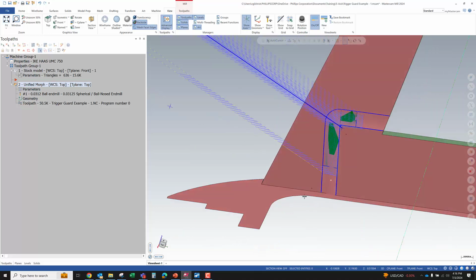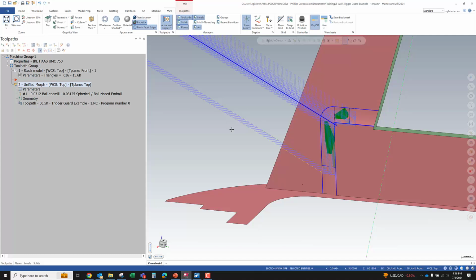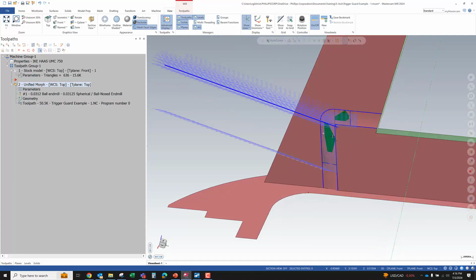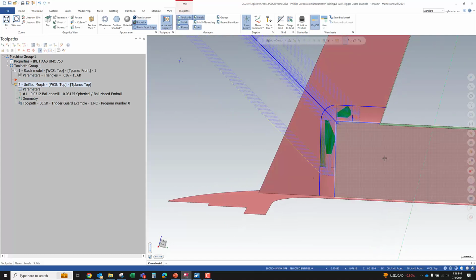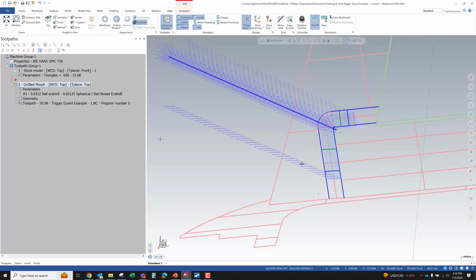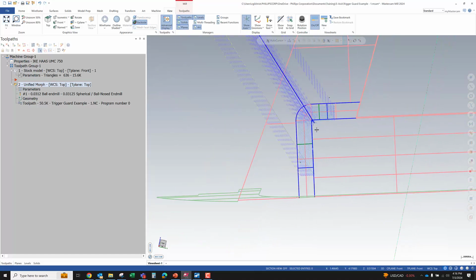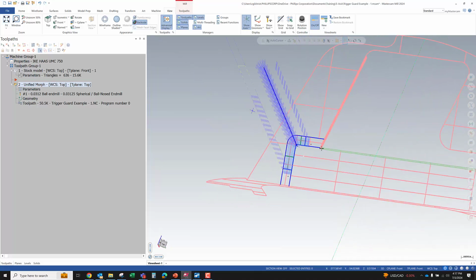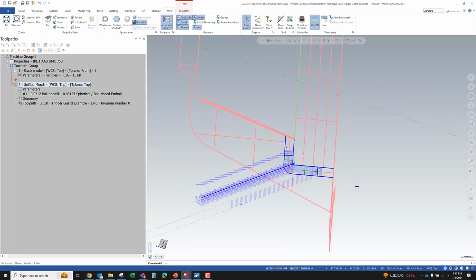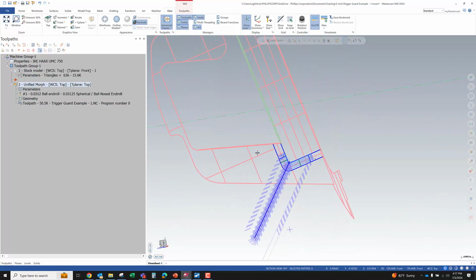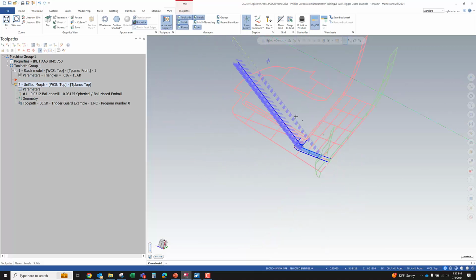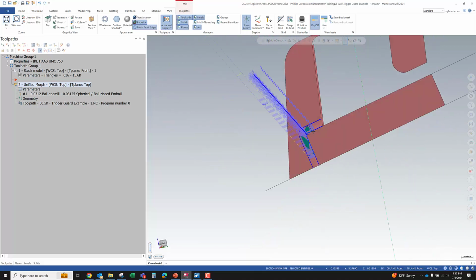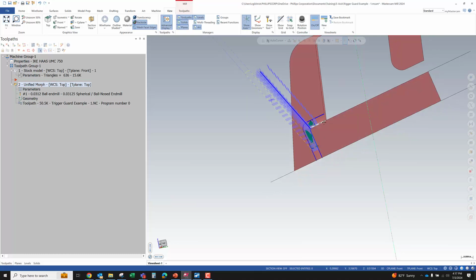So like I said, if you were running this and this has got a little overhang, so maybe when you run your wheel cutter, there's like this triangular chunk of material left over. So in a case like that, if we unshade this, you can see, there's the chain. Yeah, we may have to define it a little differently, but we could easily just chop up one of these surfaces to fit where that piece of stock was that we saw, right?